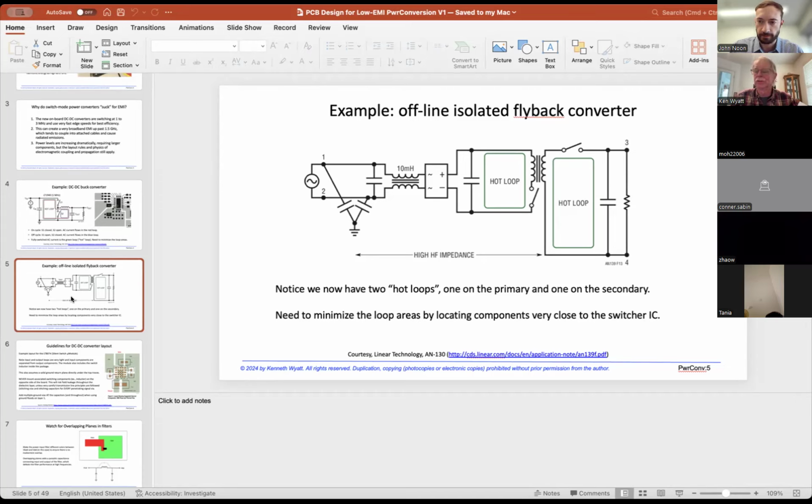Now, there are cases where you use something similar to isolate patient circuitry using an isolator. On the primary side of an isolator, you could call it one ground or one return, and on the right side a different return. But you want to make sure not to mix those planes. Great question. Generally speaking, I would just use a solid return under everything, except